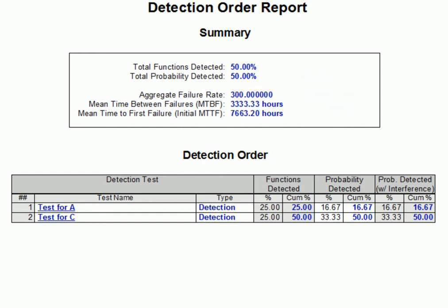The other 40% of the failure rate, of course, represents failures that we do not expect to occur, thanks to prognostics. This also can be seen in the mean time between failures, which has increased from 2,000 hours to 3,333.33 hours. This tells us that in this sample model we were able to extend the time between hard system failures by over 1,300 hours using prognostics.